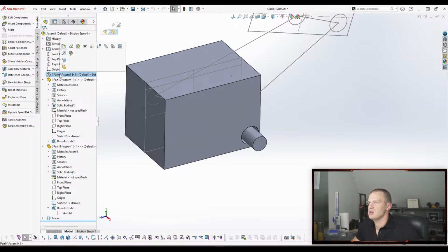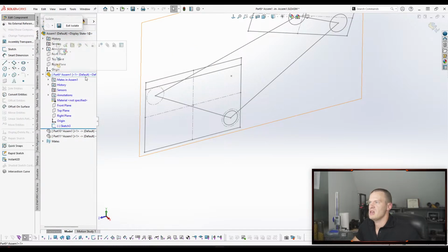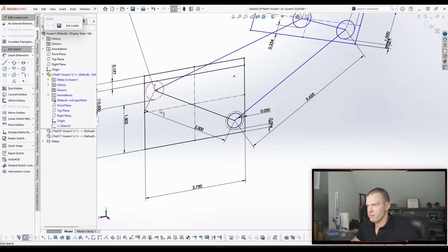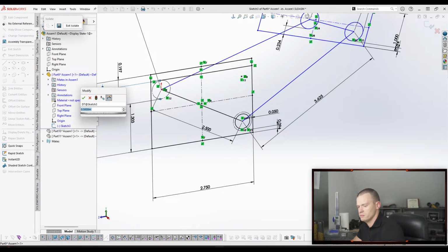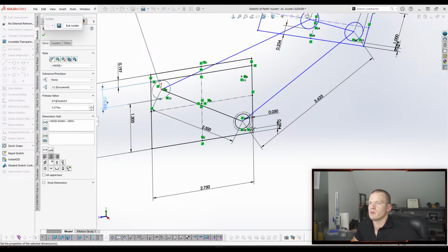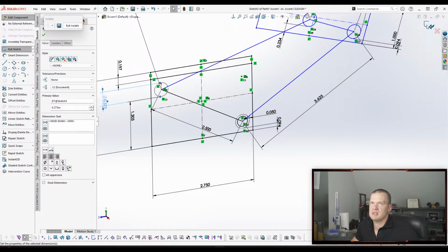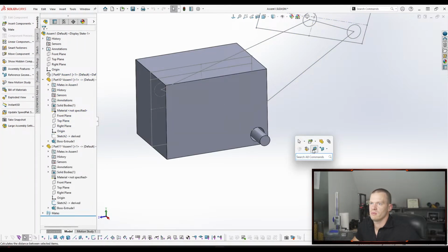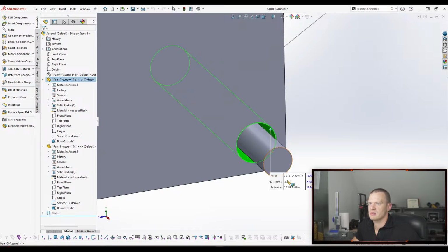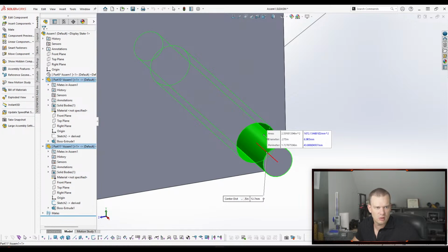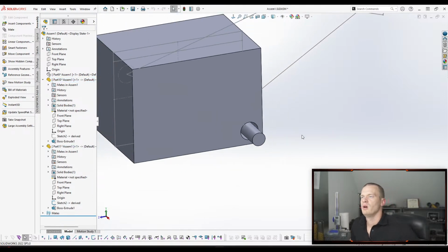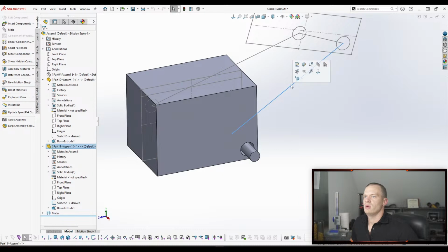So now, just as an example, we can go in here and say the factory comes back and says, hey, that diameter should actually be 3/8, not a 1/2 inch, right? We change one number, this changes, our gap stays 50 thousandths. We exit here and all this is pushed to our other parts. So now we have a hole that's 3/8 and we still maintain our gap, right? That's 1/2 inch. Minimum distance, 50 thousandths, right? So that's one way to do it, right?